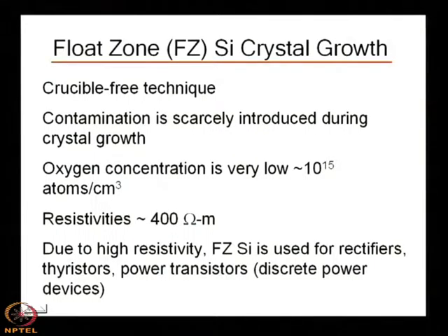So, from those materials there will always be carbon emission in the form of carbon monoxide or carbon dioxide, and they will be absorbed in the silicon melt. So, during Czochralski growth, there are many ways through which impurity can be associated in the melt, giving rise to an increase in conductivity, that means a decrease in resistivity.